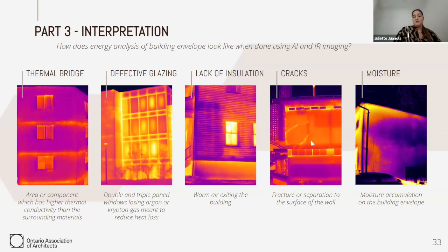So this is really interesting to property managers because this directly has an impact on the structural integrity of the building. That's the same thing for moisture. And this image is also very interesting. What you see here is an argon gas leak through the window. The reason why thermal cameras can actually spot this is because there is condensation on the window surface.